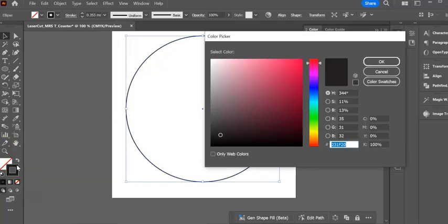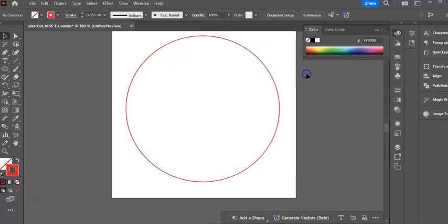I'm going to double click on that shape, and I'm going to pull this all the way up to the top and put it on the very, very corner so that 255 comes up for red. Press OK, and now when I send that to the laser cutter, that's going to come up as being the place to cut. If I put another colour in there, it's not going to read it and nothing will cut. It'll just not do anything.